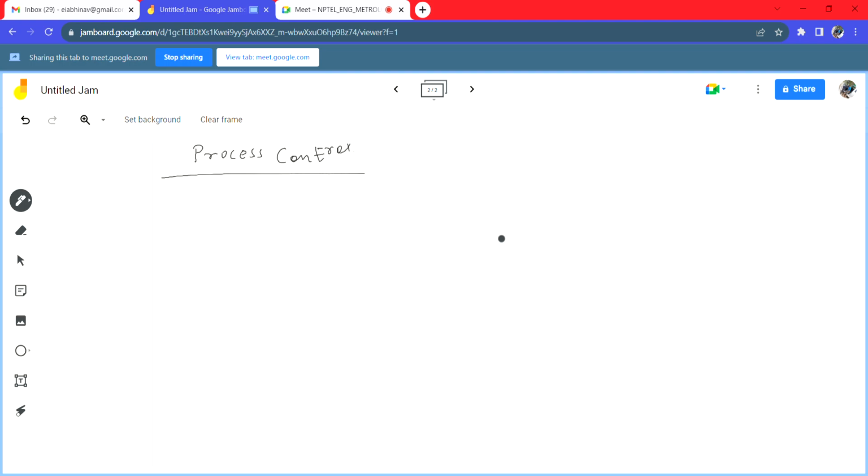So there is an input, after some processing there is an output, and it is the general convention to call such a system a control system, a simple open loop control system wherein we have input, we do some processing, and we yield an output. So this simple block diagram is a process control block diagram, and here in the instrument the processing that we are doing is called calibration.